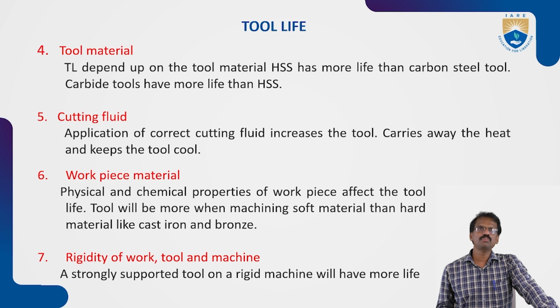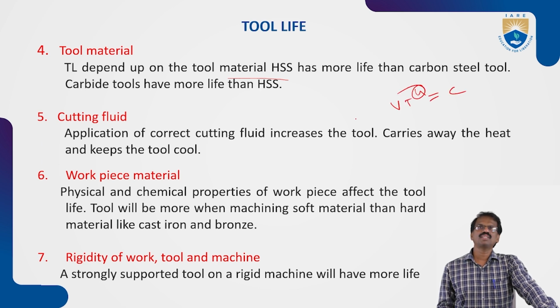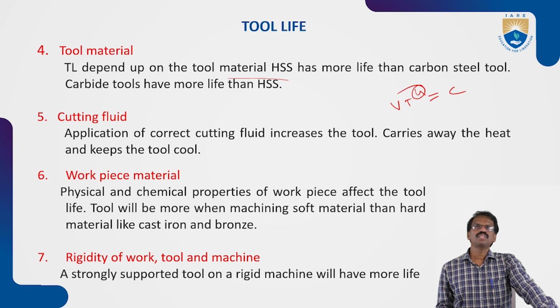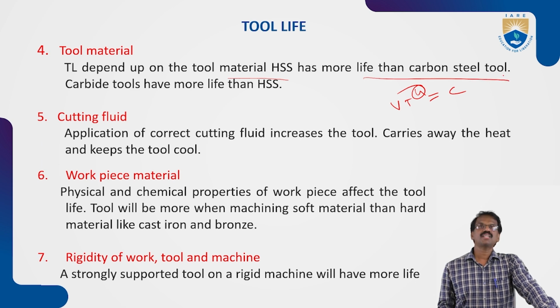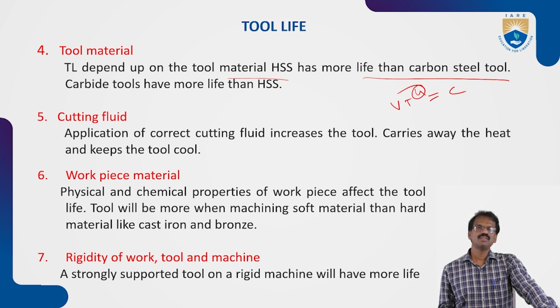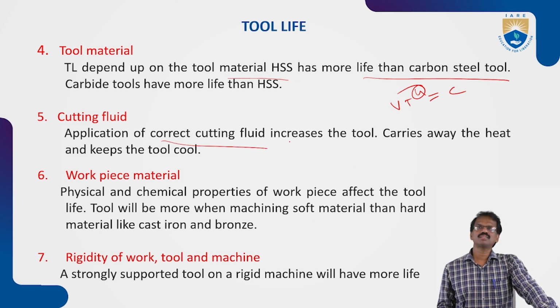Next, tool material. Tool life also depends upon the tool material, because we know the formula VT^n is equal to C. So n depends upon the tool material, for example HSS. Next, cutting fluid, a very important parameter. Cutting fluid reduces the heat which is developed between the tool and workpiece. Application of the correct cutting fluid decreases tool wear.